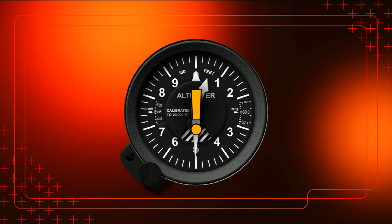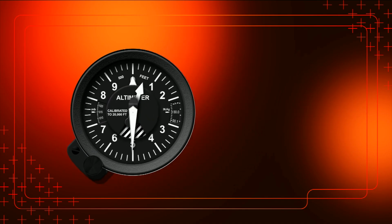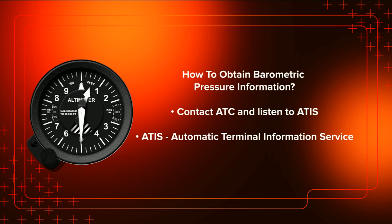It is important to note that before flight, the altimeter barometric pressure must be set, so the instrument gives the pilot an accurate ground altitude reading. This is carried out by contacting the departure airport's air traffic control or by listening to the departure airport's ATIS, or Automatic Terminal Information Service, which gives the pilot the local pressure setting of which to correctly set their altimeter to before flight.